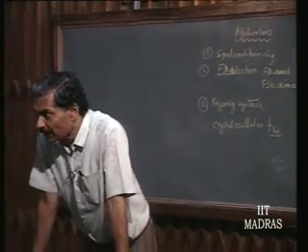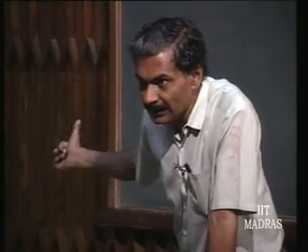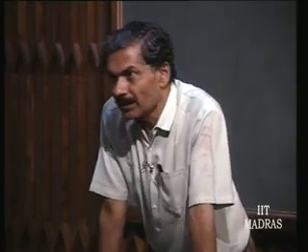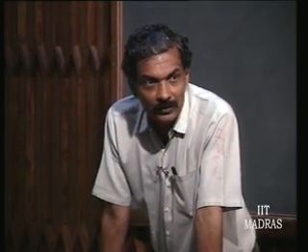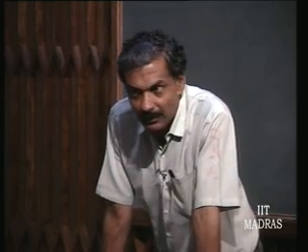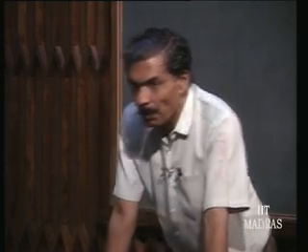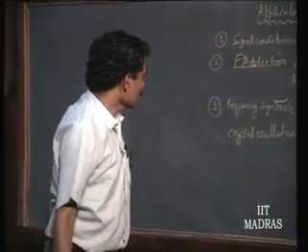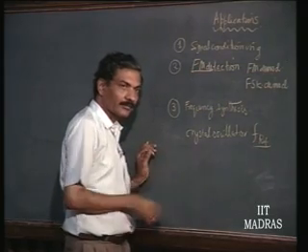Okay. It is better than a time reference. Okay. Even a time reference can be derived from a frequency reference, and therefore, most of the present day control circuitry use a reference frequency, not the good old days technique of using voltage references. Okay. So, crystal oscillator of F reference is coming.